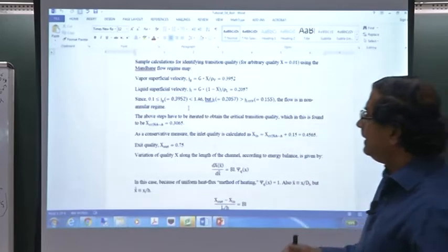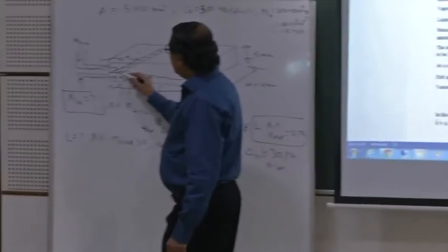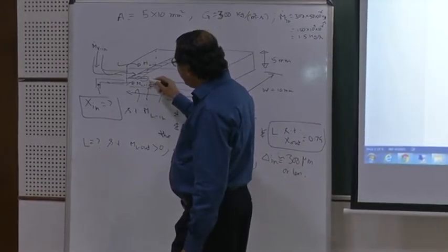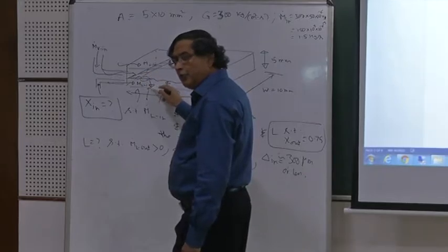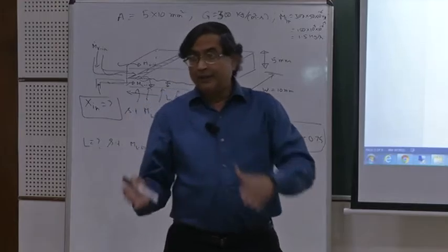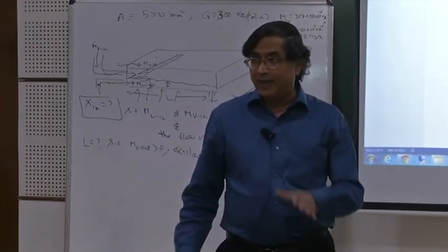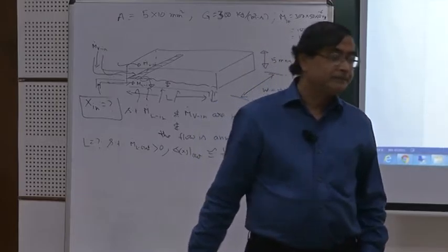If the splitter plate is around 300 micron and it comes out, you want it to be not only annular but remain around 300, 250 micron, not suddenly go to too low or too high a film thickness, because it's going to self-seek the liquid vapor interface. It's not going to be like separated by the plate. Okay.